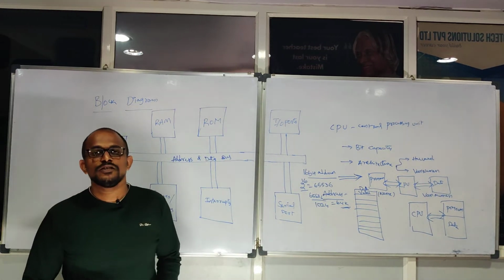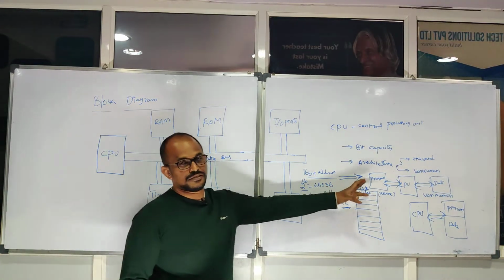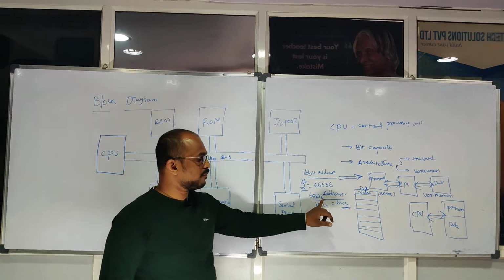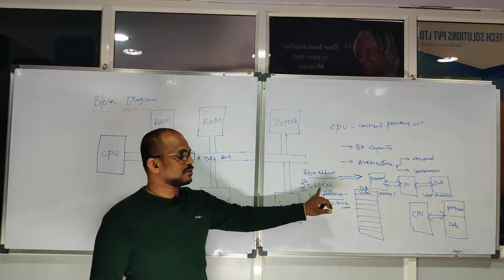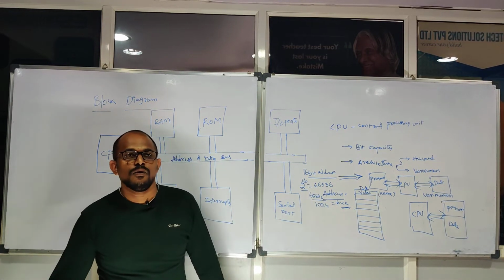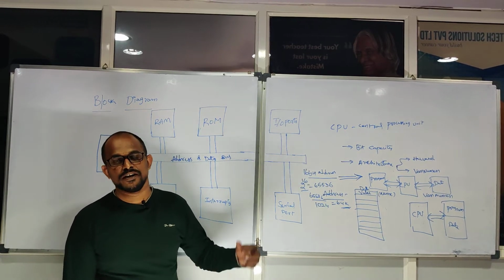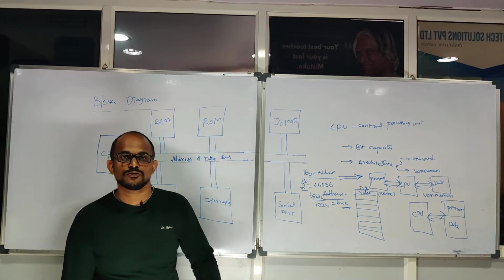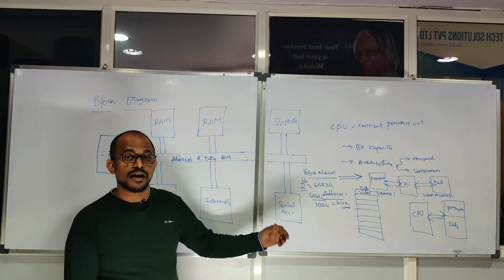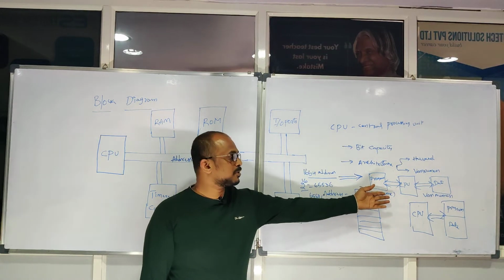So this is the importance of knowing bus sizes and bus differences. Once you have a 16-bit address bus, you can access a maximum memory of 64K. You cannot connect whatever amount of memory your application requires. So memory also has its own limitation, and that limitation is decided by the address bus and data bus sizes.